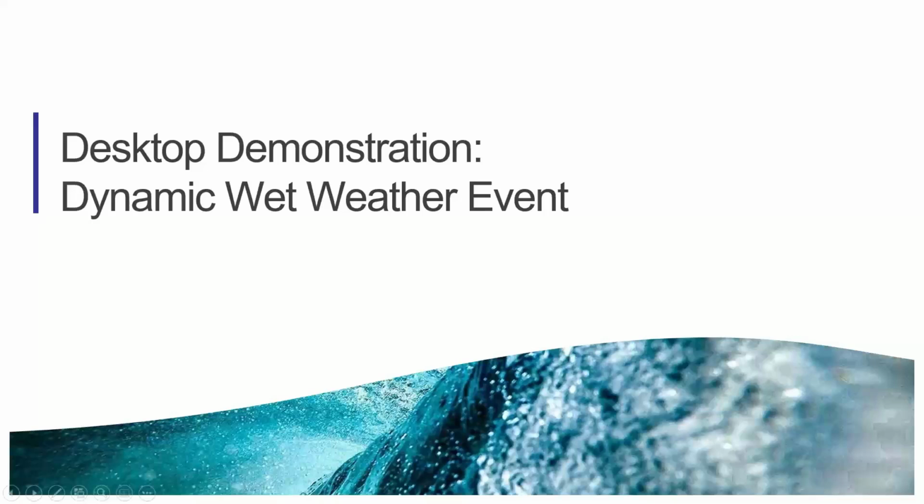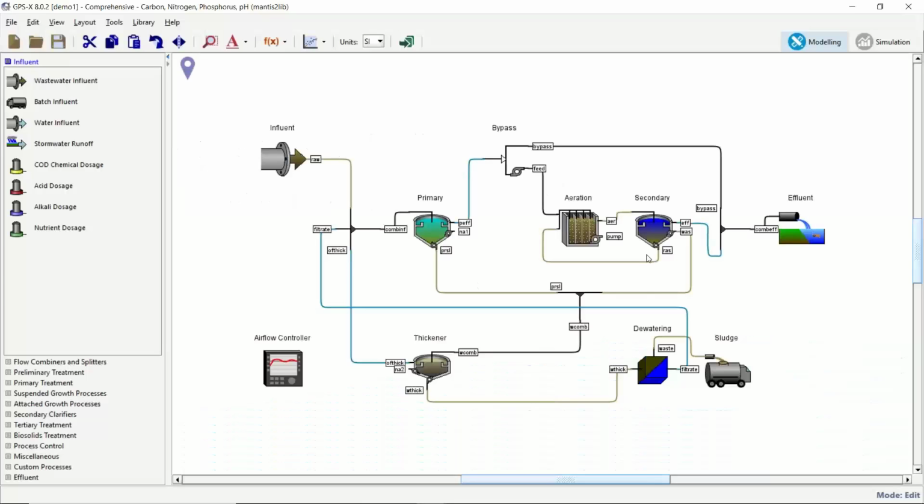Okay, so I want to start with running a wet weather event, just to get the baseline of what we're doing here. I've got my correct version open, and this is the plant that we have. Influent flow goes through the primaries, and there are secondaries, and we're not really looking at the details of the solids handling system here. There is a DO controller that we're controlling with this airflow over here.